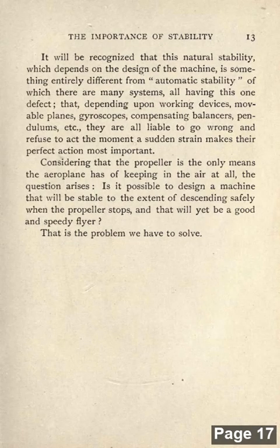It will be recognized that this natural stability, which depends on the design of the machine, is something entirely different from automatic stability, of which there are many systems, all having this one defect: that depending upon working devices, such as movable planes, gyroscopes, compensating balancers, pendulums, etc., they are all liable to go wrong and refuse to act at the moment a sudden strain makes their perfect action most important. Considering that the propeller is the only means the aeroplane has of keeping in the air at all, the question arises, is it possible to design a machine that will be stable to the extent of descending safely when the propeller stops, and that will yet be a good and speedy flyer? That is the problem we have to solve.